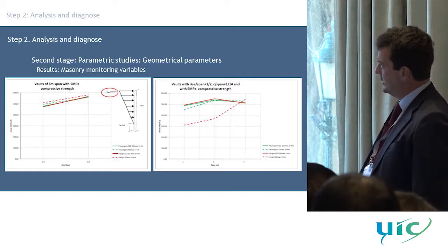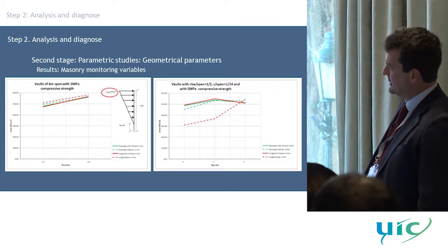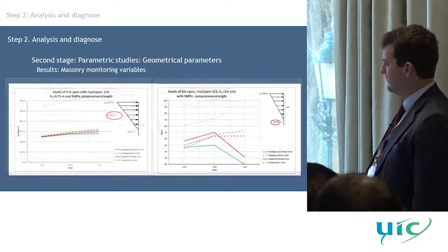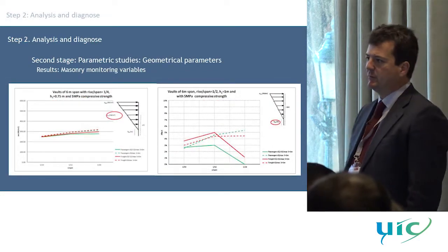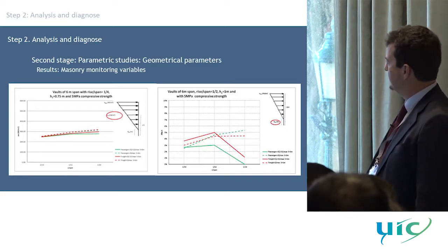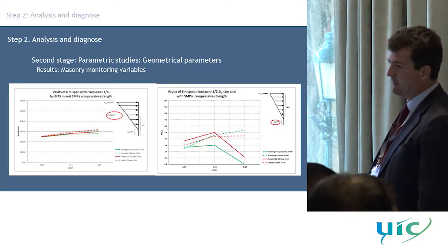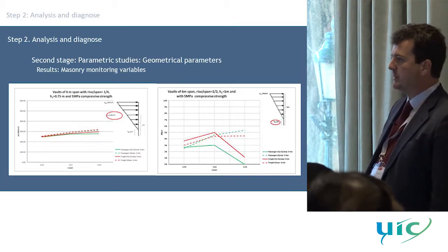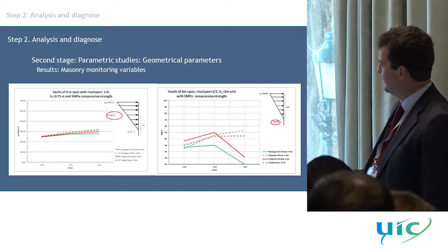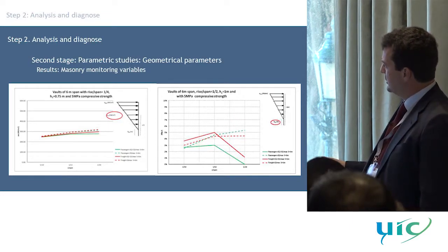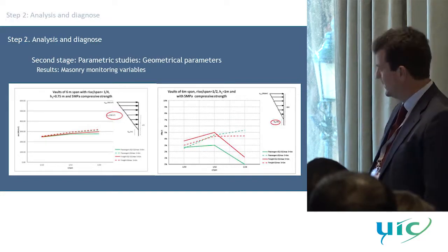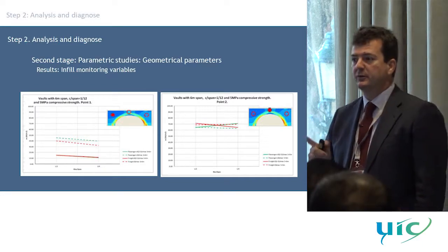No? We did quite a lot of this. Different rise to span ratios, and this is the peak stress that you have for a 6-meter span. Well, all of this again is in the background documents. Here I have brought some of the values. We have very little cracking also for this ratio of slenderness. So for normal traffic with well-compacted infill, with good masonry, not a lot of cracking is expected, 5%, 6% of the section. And remember, these are 2D models.